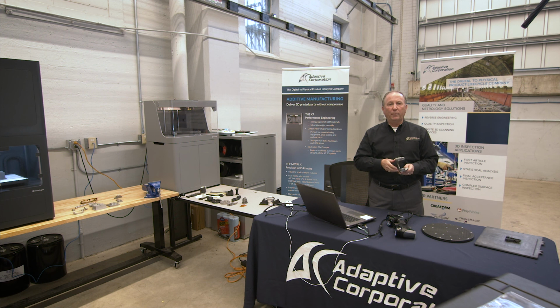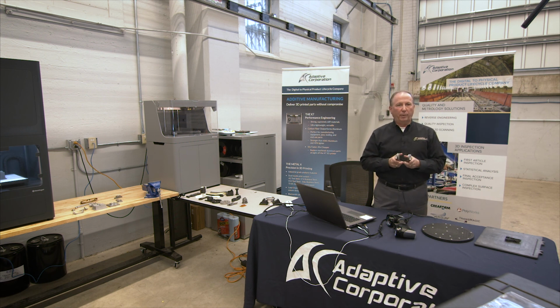I also might mention that we have a lot of customers that employ what they call hybrid inspection. Say this were an aerospace part and it's got 100 dimensions that I have to inspect, but maybe only 10 or 20 of them have to be to a tolerance of 5/10 of a thou. A lot of our customers will do a first pass scan with the 3D scanner and get a green light.